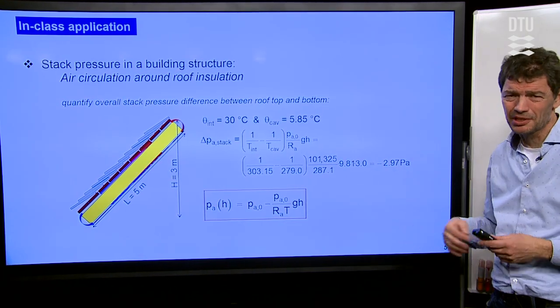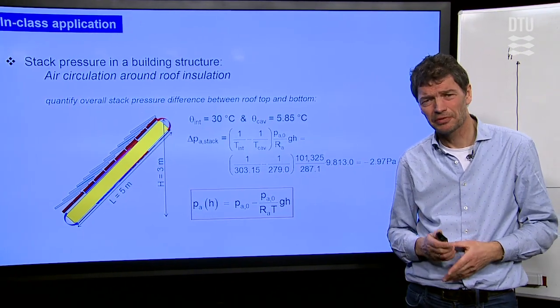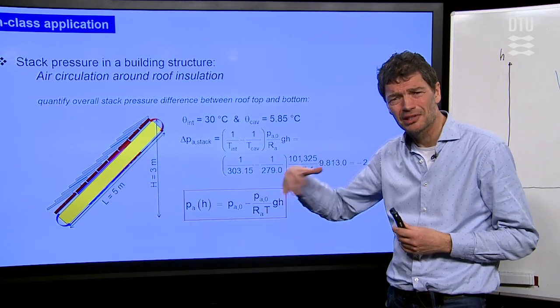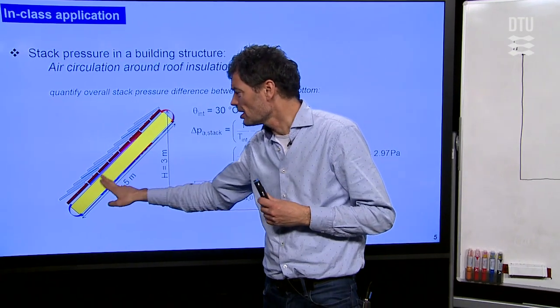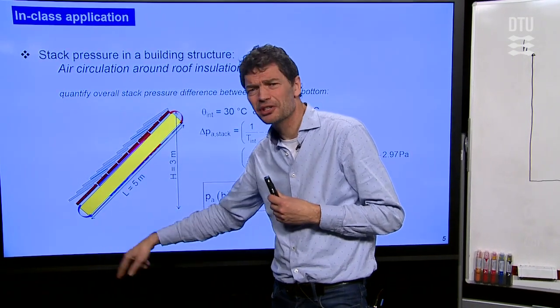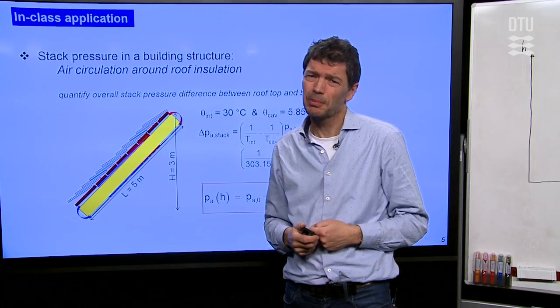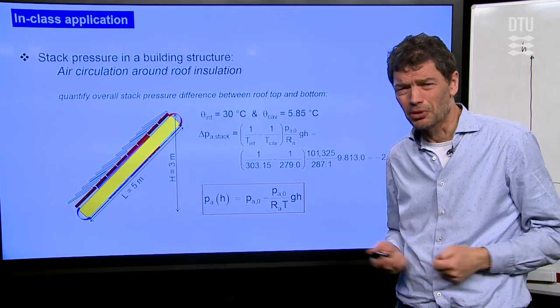It doesn't sound like much compared to the atmospheric pressure, which was 101,325, but it's an air pressure difference that continues to be there as long as we have the temperature difference, and enough that we can calculate hydrodynamically how much air circulation this will cause. So therefore, it's significant to be able to make these calculations of stack effect, although they may look like being small